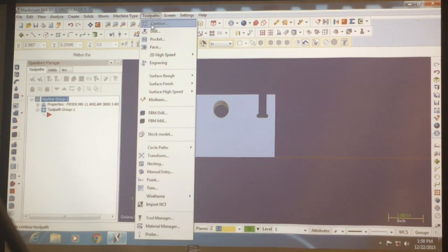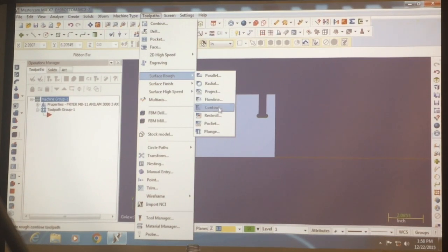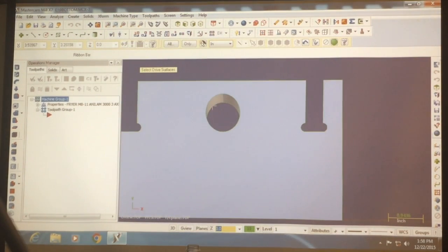So toolpath, rough, contour, check. Can you explain why it's rough and not finish? Yeah. So the reason why I'm doing rough rather than finish is it's just the difference in step down. Honestly, between rough and finish there isn't much difference. The difference is, let's say if you were to use another operation and there were different levels, it would take the step downs and the step overs in smaller intervals. That's the difference, literally, between rough and finish.